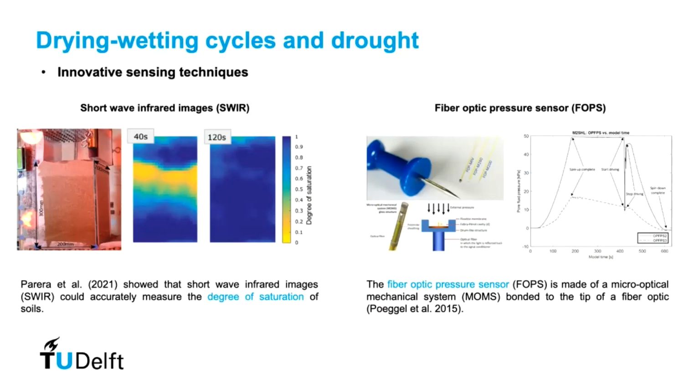And this is very important in small scale models, because imagine we have to place a sensor that can act as an anchor to the soil. Therefore, we might be misleadingly seeing that the whole system is relatively stable, while it's just the cable that is reinforcing it. So by doing this indirect measurement, we avoid putting sensors inside the model, and we have a richer set of information on the saturation along the soil and along different water soil wetting conditions.